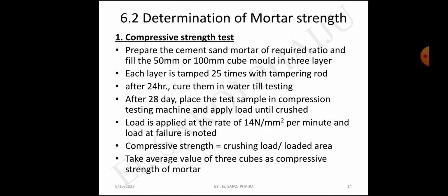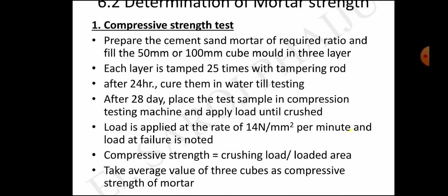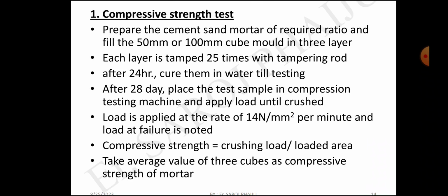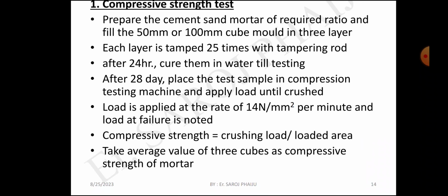6.2 Determination of mortar strength. Compressive strength test. Prepare a cement mortar of required ratio and fill a 50 mm or 100 mm cube mold in 3 layers. Each layer is tamped 25 times with a tamping rod. After 24 hours, cure them in water till testing.